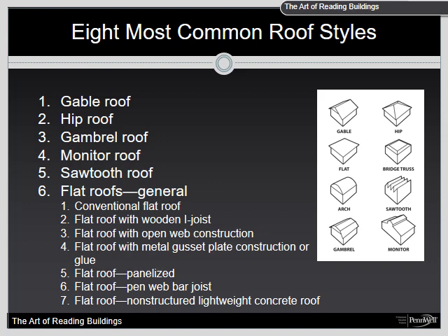Although not as common as it used to be in gable roofs, in lightweight construction, the construction materials, both wood and metal, are similar to those used for gable roofs. Various degrees of pitch and roof coverings are characteristic of this style of roof. Strengths. In conventional construction, the ridges and rafters are 2x6 or larger. The ridgepole, valley rafters, hip rafters, and the area where the rafters cross the outside wall are the areas of greatest strength.